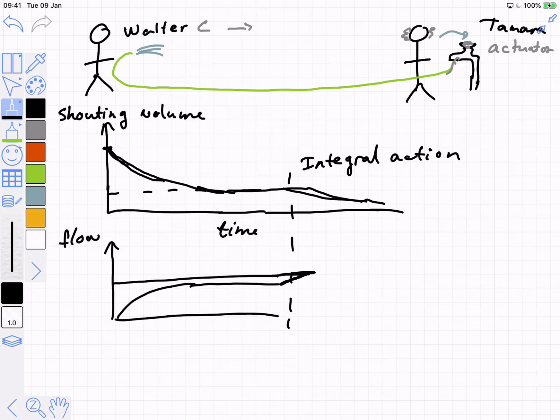And then it doesn't move. You don't just say, oh, I pulled at that amount and it didn't move. You pull harder, and you keep pulling harder until it moves. So there's a lot of these things where you are adding on over time because it hasn't done what you want yet. You're taking larger action, not because the error has changed, but because the error hasn't changed for a while.